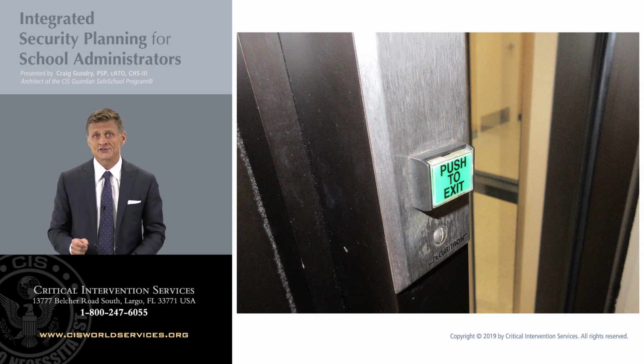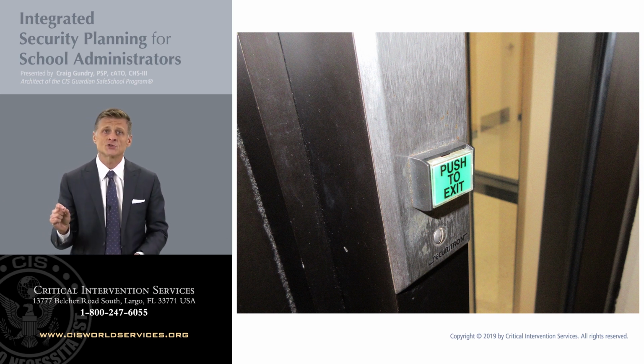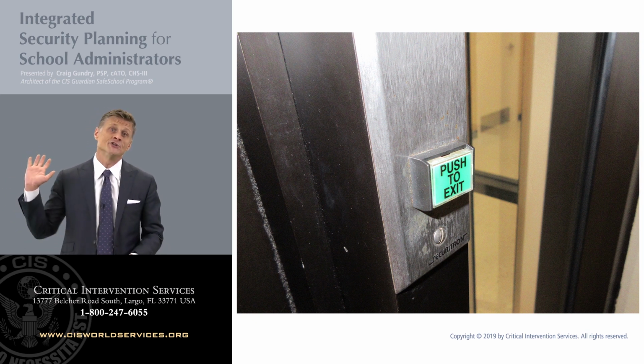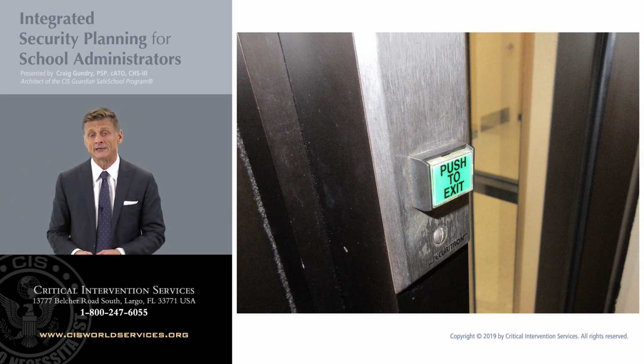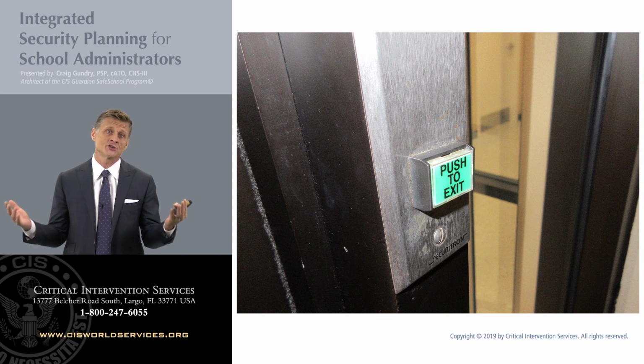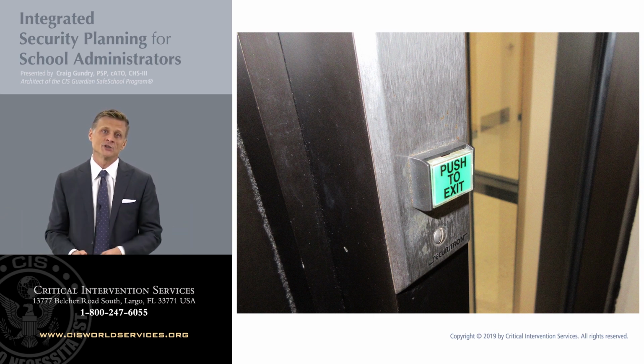I have also run into some situations where that push-to-exit switch was actually mounted on walls opposite the location of the door or gate it was supposed to operate. The only person who would recognize the location of these push-to-exit switches under high-stress conditions would be staff that were already familiar with the operation of these doors and gates. This is very problematic.